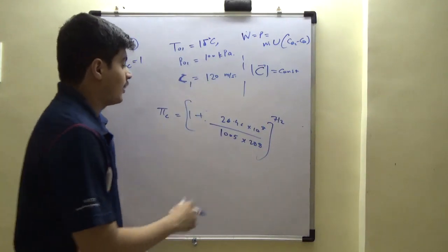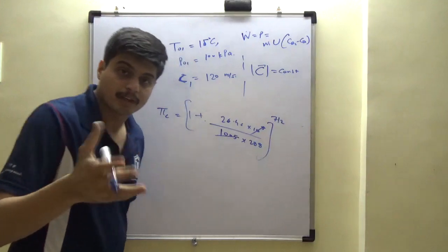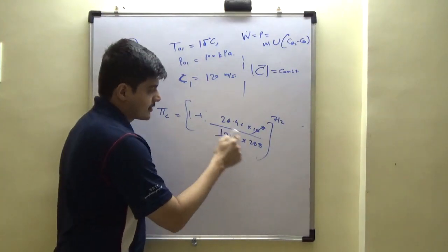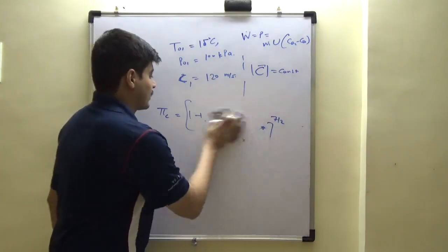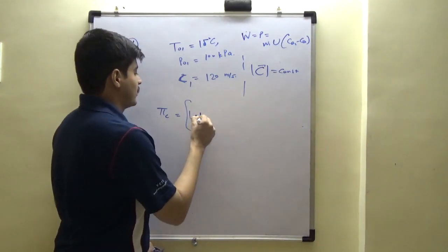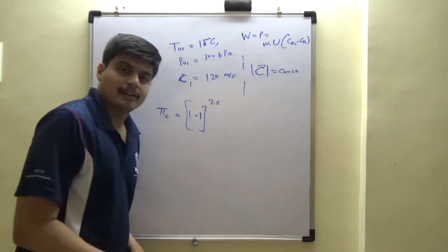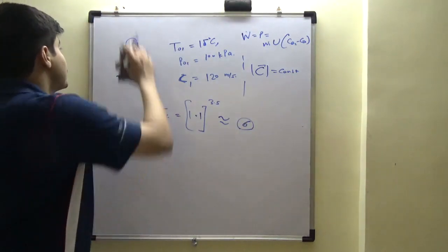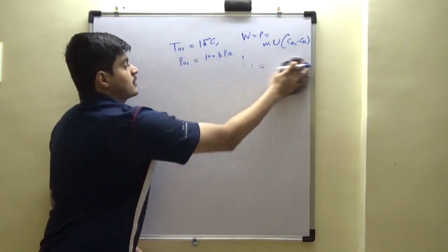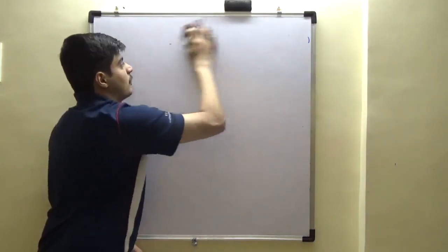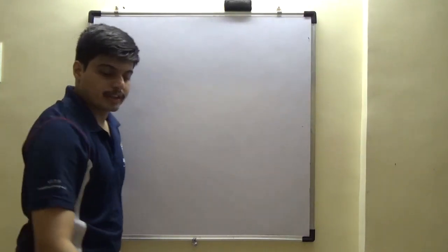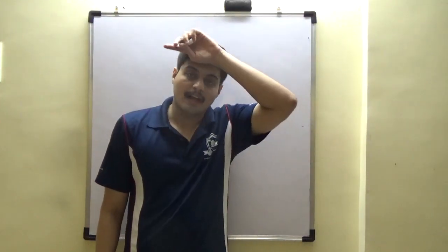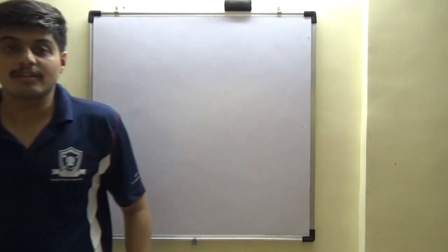Now this is a simplification game to give you a ballpark range. This is about 0.1. So this becomes 1.1 raised to 3.5. This would approximately give you 6. Which means for this given compressor with these parameters and this turning angle, the compression ratio achieved, P03 to P01, is 6. And so P03 you would get at stagnation is 600 kPa. That was the other question.